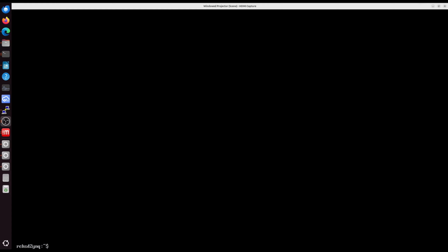And that I did. There's a command you can do, an alsactl store. So like right now, if I like the configuration I have, I can do an alsactl store, and probably have to do a sudo on that. But that stores the configuration, which I can then copy over into my Petalinux build if I want, and then it will restore that every time.